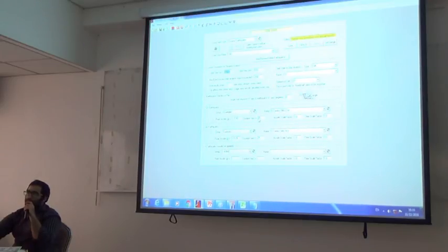So if this is 25, and you want to increase the time of the analysis itself, what happens is that after the duration of the ground motion finishes, all of the data becomes 0. So then no more force is being applied, right? You just simply increase the time of the analysis. There's no need to change the time of the ground motion itself, for you to have a residual drift after some free vibration cycles. Only that.